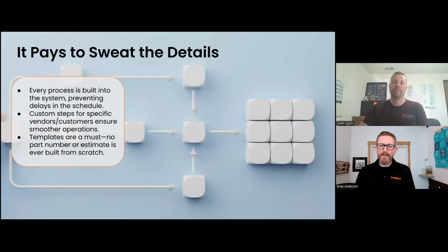So what was happening, we would receive the material in-house, they would check off the PO, and then it was my machinist who was finding that ultrasonic inspection wasn't being done because he saw the work stoppage. So we did some additional training. And now our receiving individual is checking every single work order to see if there's additional material steps that need to be done. That way, material doesn't sit on our floor for a week before we get it to ultrasonic and it's the machinist telling us the problem. Now our receiving team is the one finding that problem. Yeah, that's great. Find the problem in the right spot.